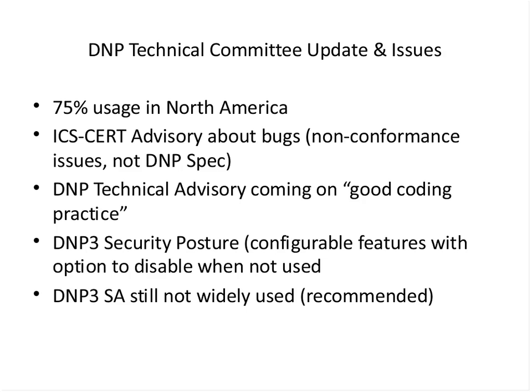So a couple of things I wanted to say about the DNP. One is that there have been some advisories out about some bugs that were found, but what the DNP Technical Committee found upon deeper review is that it was mostly non-conformance to the DNP spec. In other words, how it was being implemented at a particular utility was not in conformance with the DNP spec, and it was not an issue of the spec itself. So it's recommended that there are bug fixes available for that, and for those utilities to go ahead and correct that.